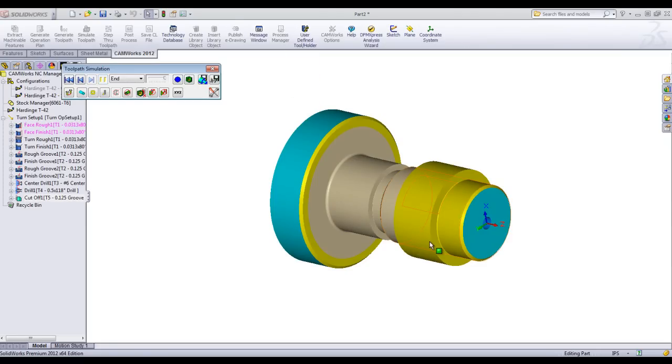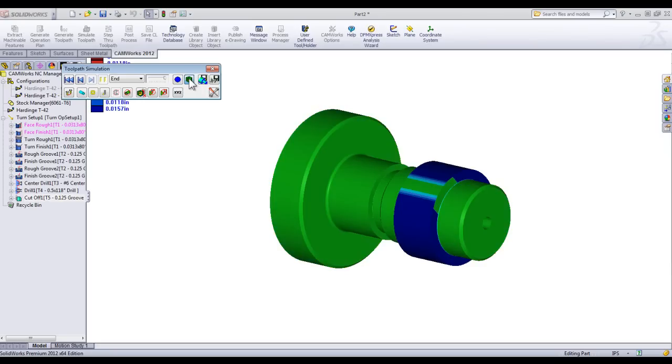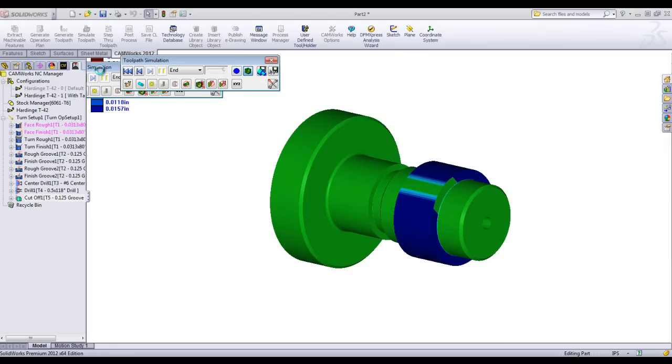Another neat thing about working right inside SolidWorks is that we can use the intelligence of it having a solid model. So I can compare the SolidWorks model with this verified model here, and it shows up with a little chart over here. Blue means that there's still material, red would mean that there's missing material, and green means that we are right on the mark. So you will see here that there's our little tab showing up. This is very neat when it comes to working with this kind of stuff.